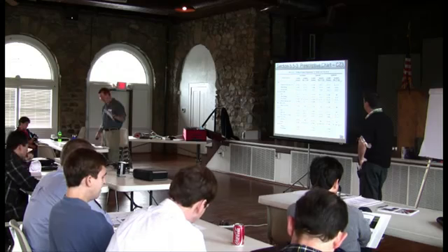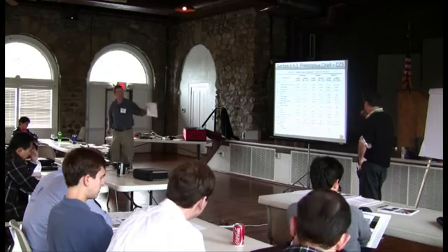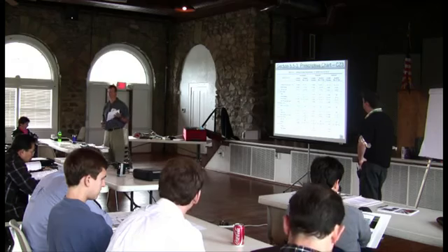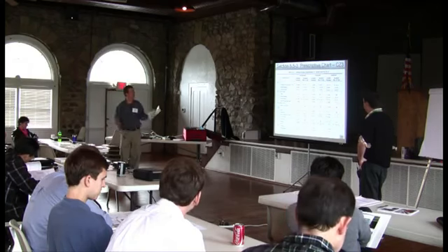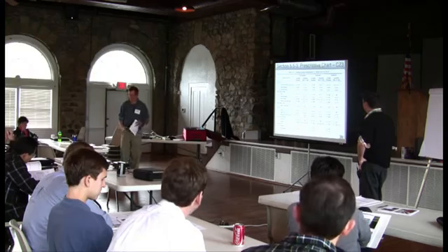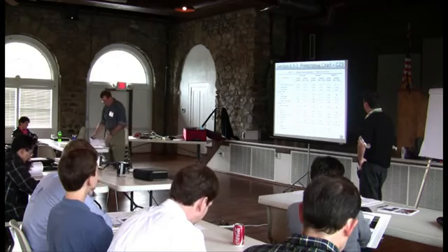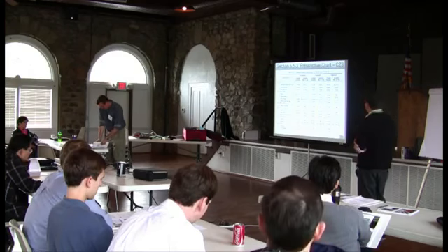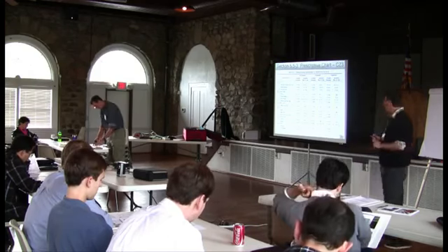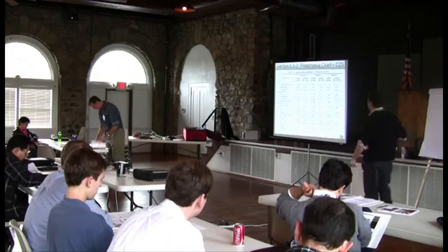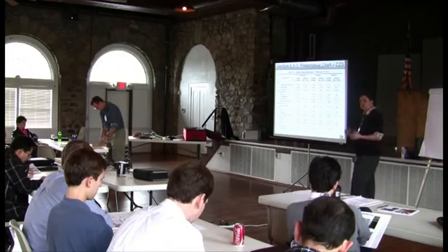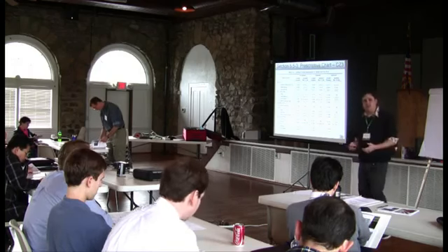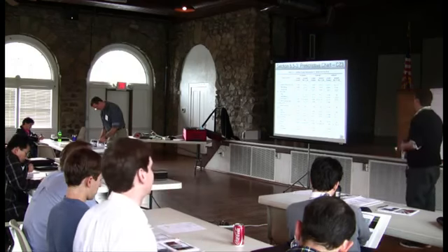So you've got this entire table in the back. The top half of the table, which is what you see up here, is the opaque part. The bottom part of the table is glazing. So, Brandon, let's focus mainly on this part, which I think is where most of our commercial buildings lie. You've got three conditions for roofs. Insulation entirely above deck needs to be an R20, and it's got CI. CI stands for continuous insulation. Metal building, R19. Attic and other, you need to have an R38 or greater.